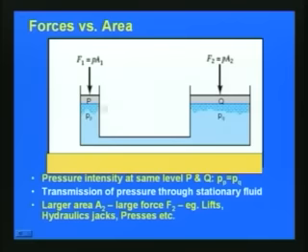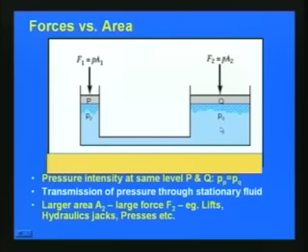By applying a small force here, we can obtain a larger force there. So this principle is used in lifts, hydraulic jacks, presses, etc. What we are doing is applying a small force F1 here, which gives correspondingly a large force output; the input is small and a large force output is produced, which is used in lifts, hydraulic jacks, presses and many other hydraulic equipment. This principle is very important in fluid statics, which is based on the theory of the transmission of pressure through stationary fluid.